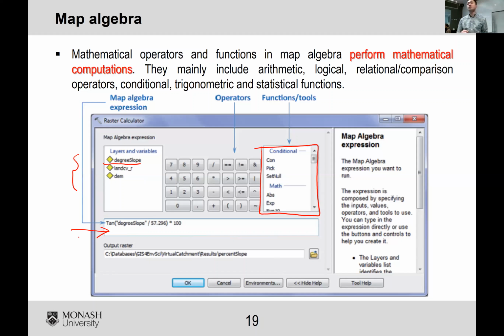For example, if there's a relationship between the degree of the slope and the cost to build a wind turbine there, then it has to be represented by a function first. Then here you can get the slope degree input from the slope layer, and implement the function here to get the cost result. In that process, the output will be a cost raster. Okay?